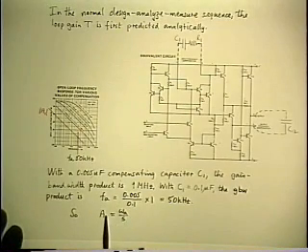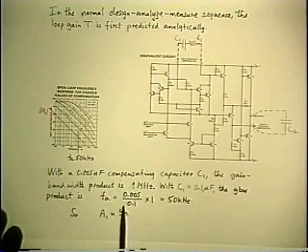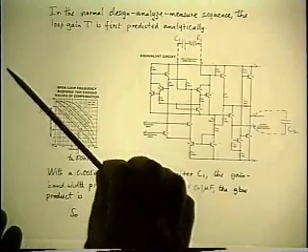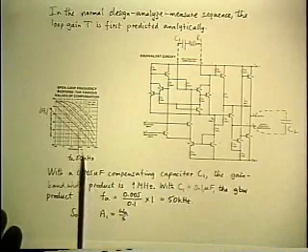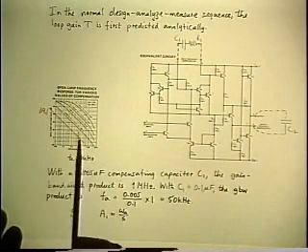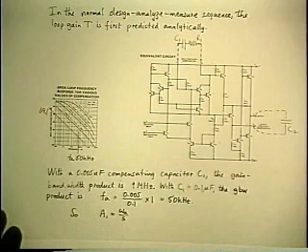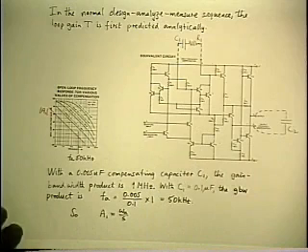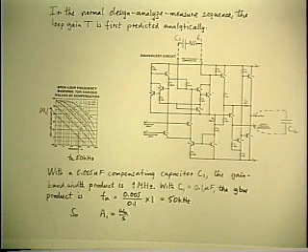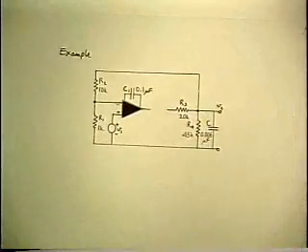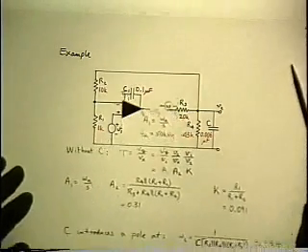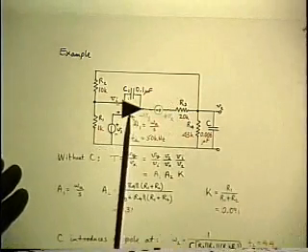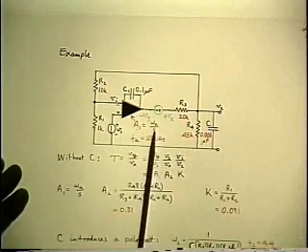So the expression for the gain of the op amp is simply omega A over S that specifies a declining single slope, and the omega A is the frequency where the magnitude goes through unity. That's the unity gain frequency. That's all I need to represent the gain of the op amp. So I can go back to the diagram now and draw that in. So I've labeled the gain of the op amp, A1 is omega A over S.